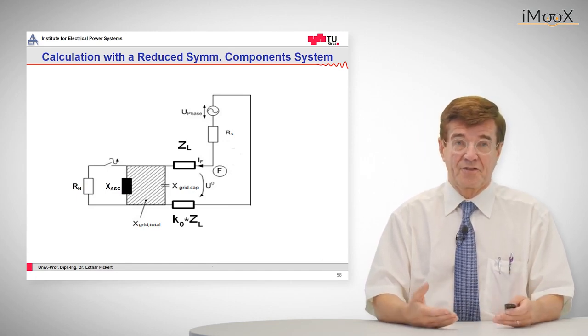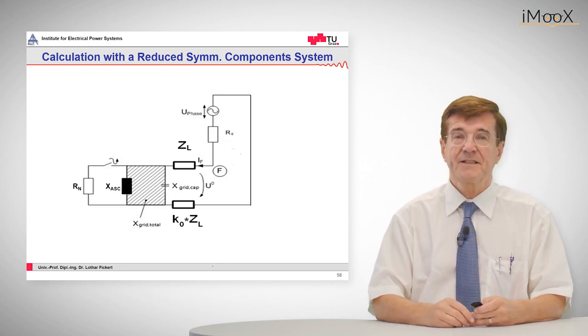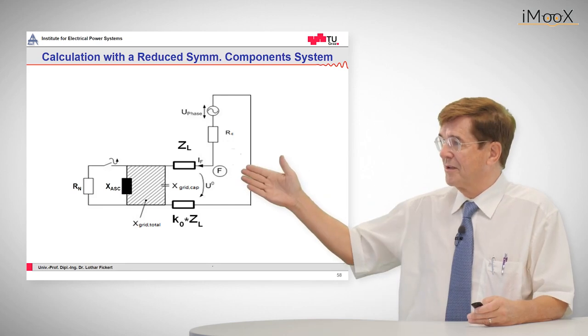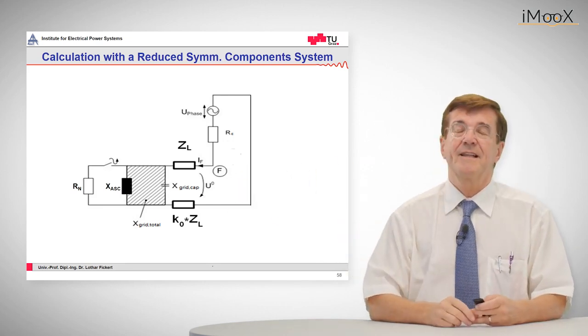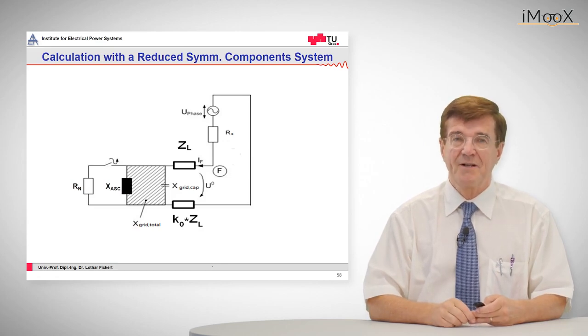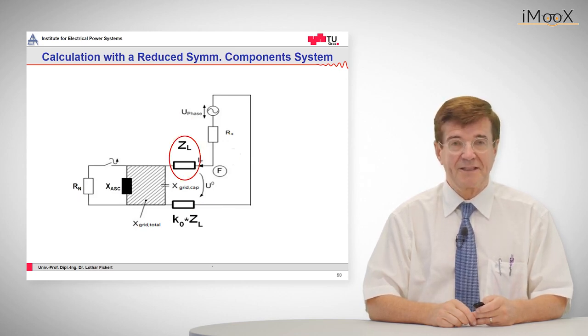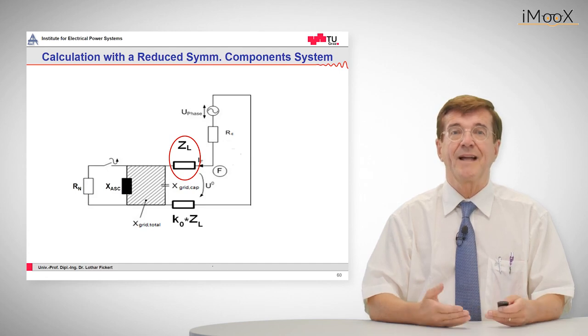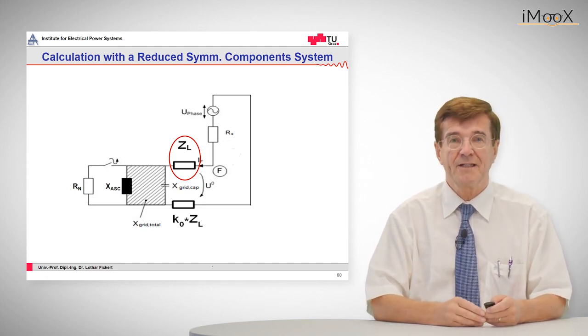Also the short time low impedance resistor is indicated, and between the fault point F and this parallel circuit we see now that the line impedance plays in this case quite a considerable role. So again, this is the neutral system, and we concentrate on this role of the line impedance and the return path for this line impedance of the faulty line.